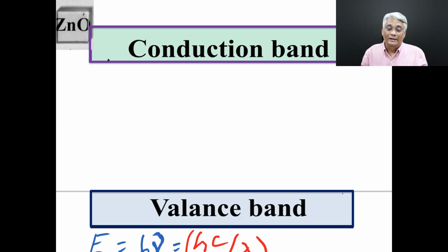That's where this class of wide band gap materials comes in. Indium tin oxide is one of the well-known TCO, transparent conducting oxide materials, but indium is expensive. So there are alternatives. Zinc oxide, aluminum doped zinc oxide, we can make into a transparent conducting oxide.